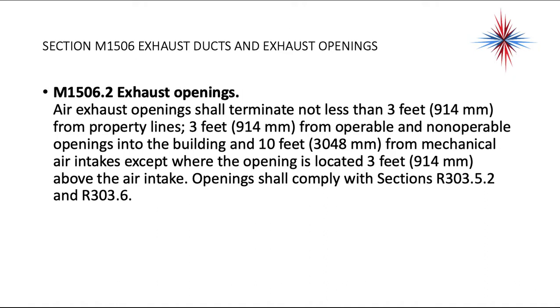Again, we don't want to bring in the grease, smoke, and odors that are being exhausted. Makes no sense. So that's what the 10 feet for mechanical air intake is about. So if you have makeup air being pulled in, you need to make sure that it's 10 feet away or 3 feet above that air intake.